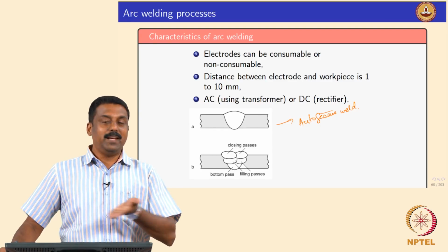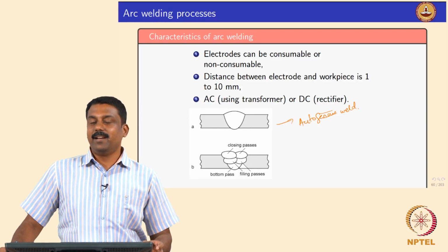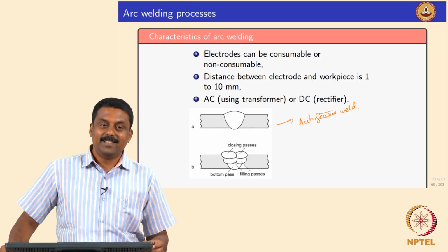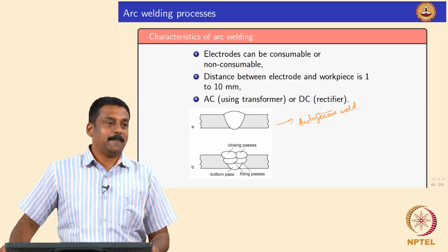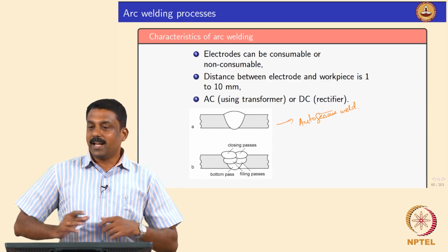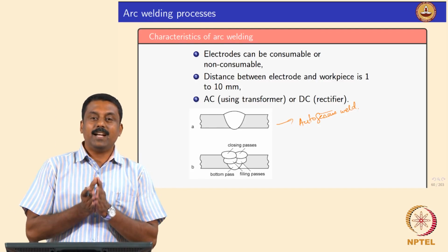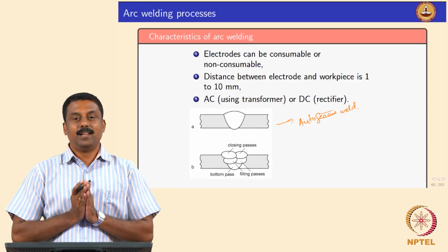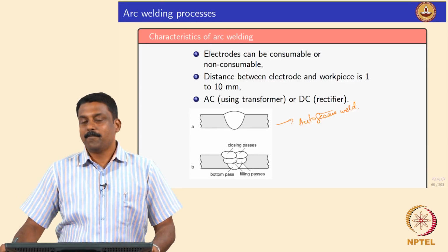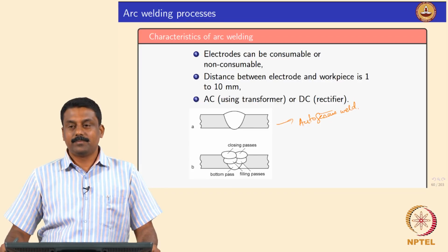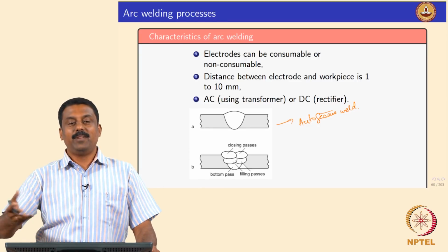So the field strength determines your JE. We always say that the welding is carried out at 200 amperes, we never say 10 volts, it is meaningless because voltage is a derived quantity, we derive voltage from it. So the current is rate controlling. When you say that the current is important, I welded with 100 amperes or 120 amperes, the voltage is irrelevant. So you always use some E, the field strength, to generate JE, and that will determine your heat generation.